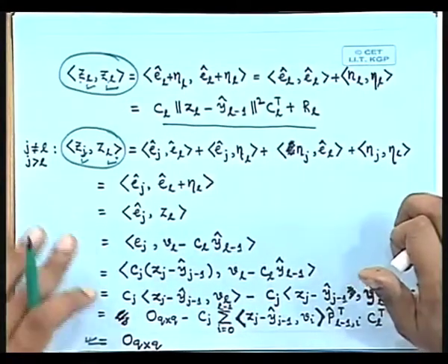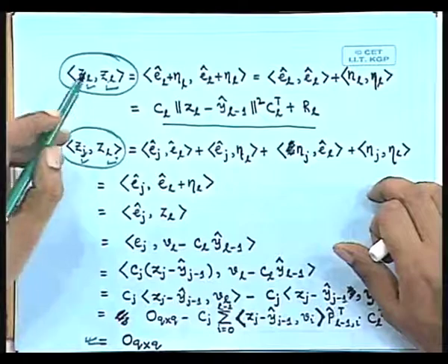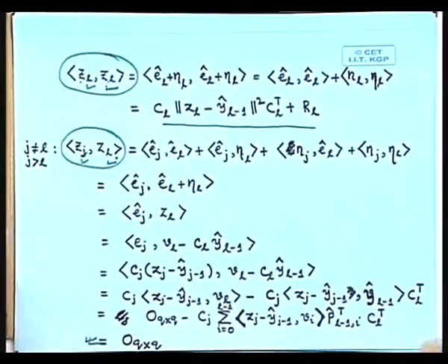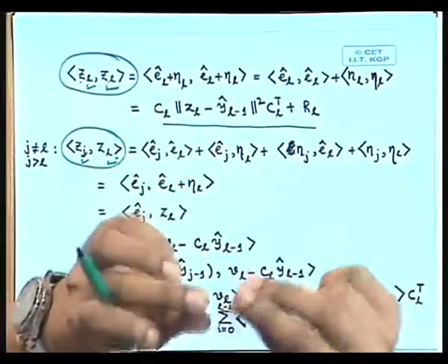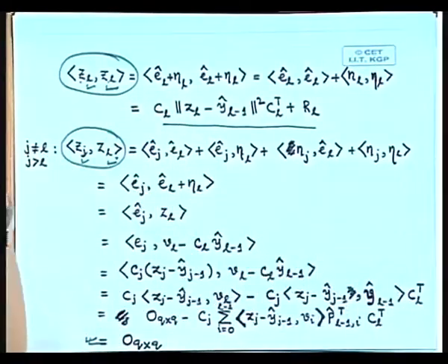So what have we done in effect? Rather than using the measurements, we have created an alternative sequence called innovations, which is linearly generatable from the measurements, but which is white. Now obviously, if you deal with white sequences, all our analysis will become simple. That is the advantage.